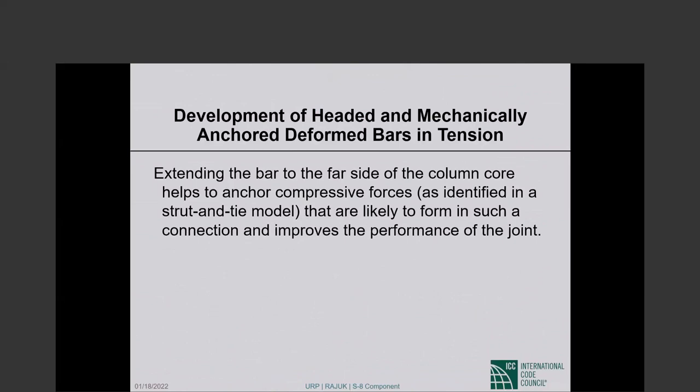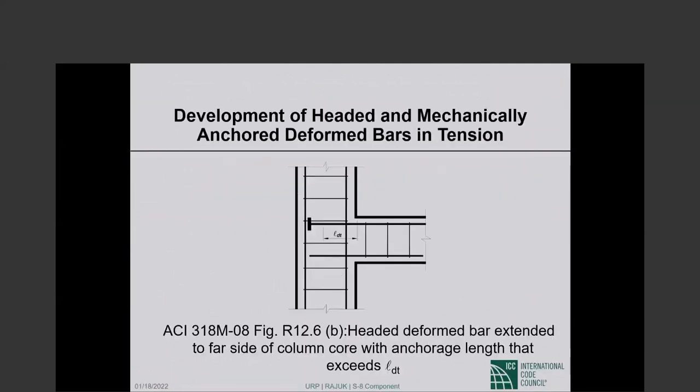Okay, continuing with development of headed and mechanically anchored deformed bars in tension, extending the bar to the far side of the column core helps. So there is one slide of writing, and what this is saying is something very sensible. Let us say you are developing that bar. L sub dt. So there has to be full development beyond the face of the column.